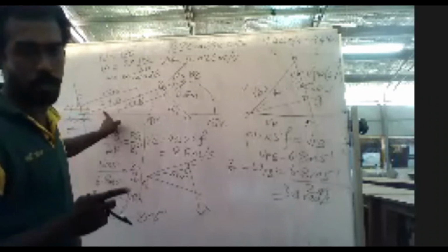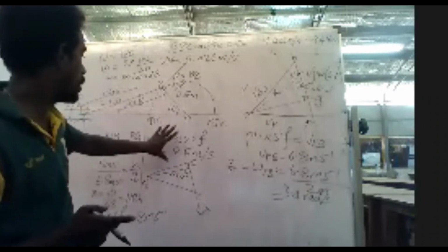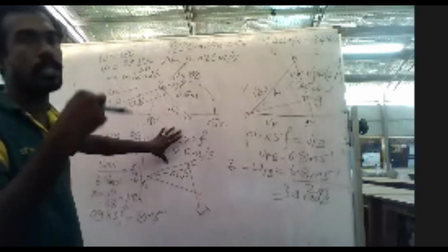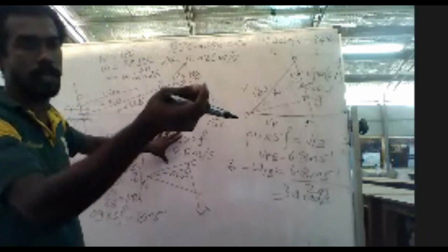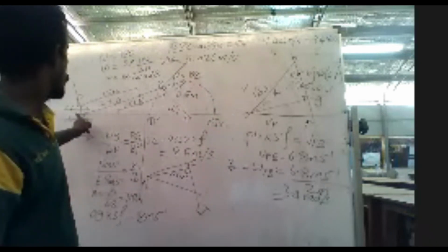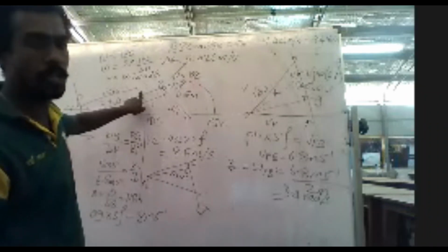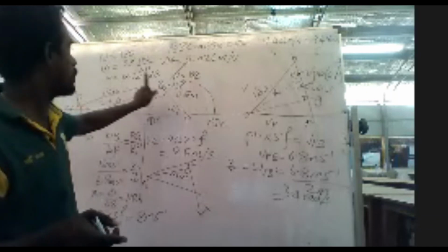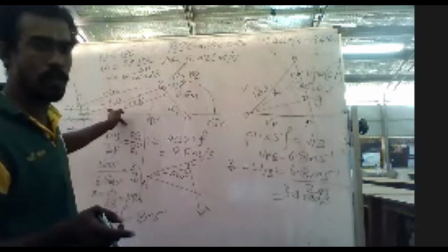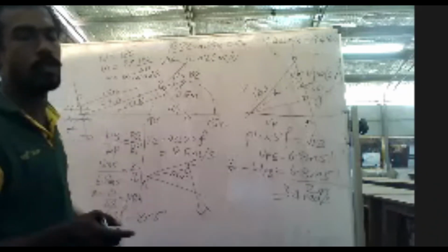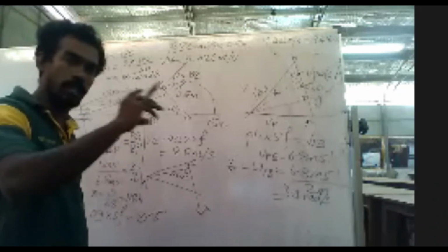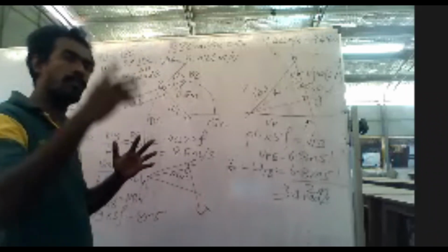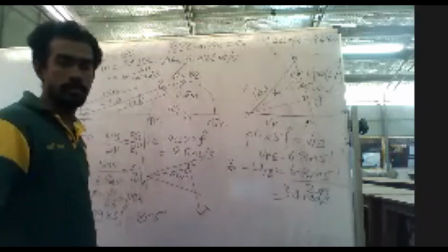In the previous case, we were discussing the point E. In that one, the question is given from the gudgeon pin, the point E is 1.5 meter. So gudgeon pin is here. From gudgeon pin, the point E is 1.5 meter. This question is from crankshaft, the point G is 1.47 meter, right? We need to pay care on that, from where we are measuring. That's what relative velocity means, based on which point we are measuring the other object, right?